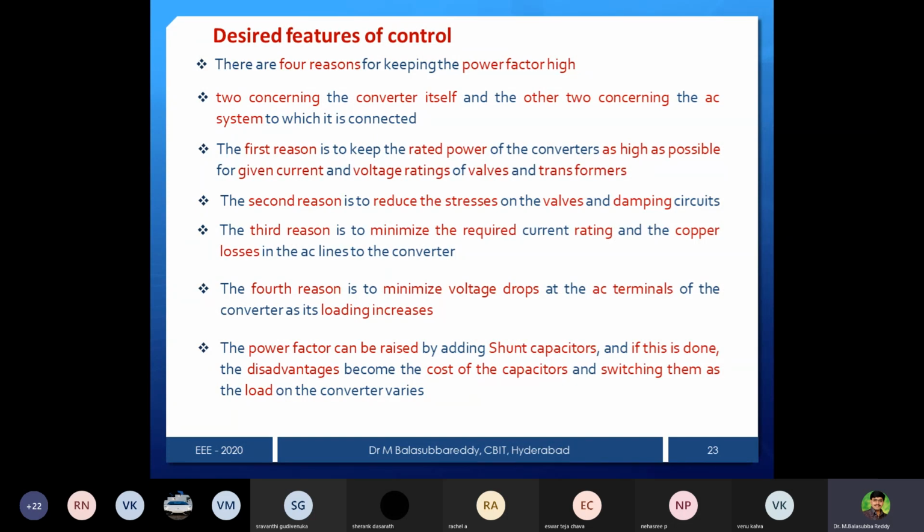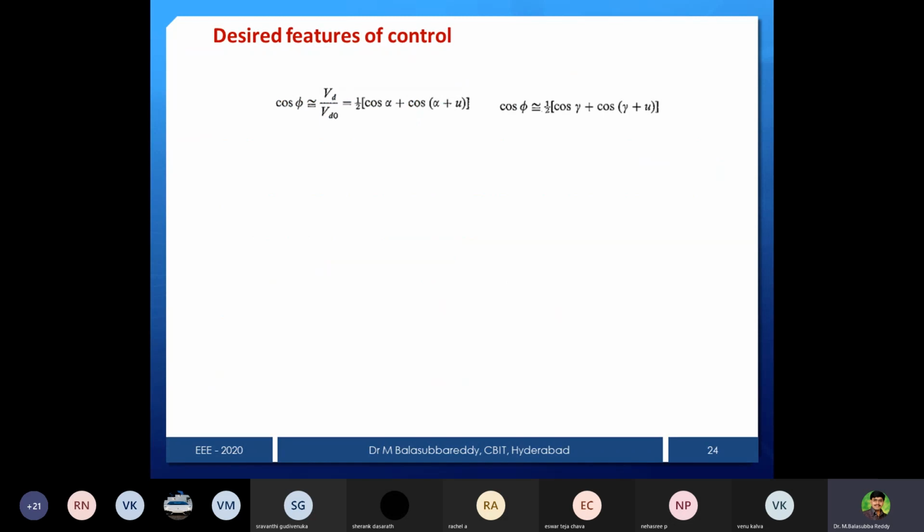So that is not a fixed condenser; through switching action there are many condensers, and depending on our requirement of the reactive power, you can switch on the capacitor. Whether you use more or fewer capacitors is decided by the load.